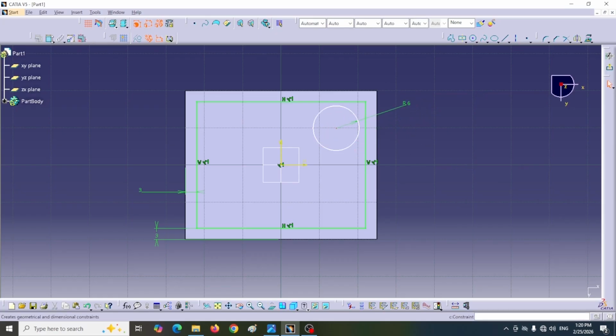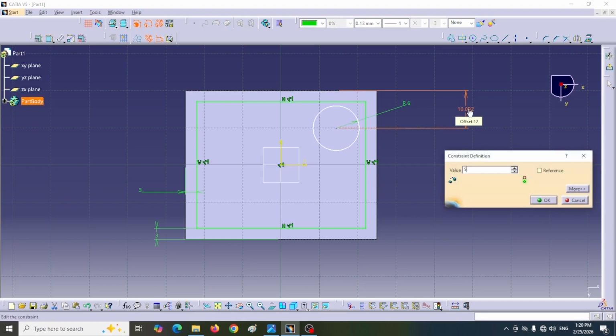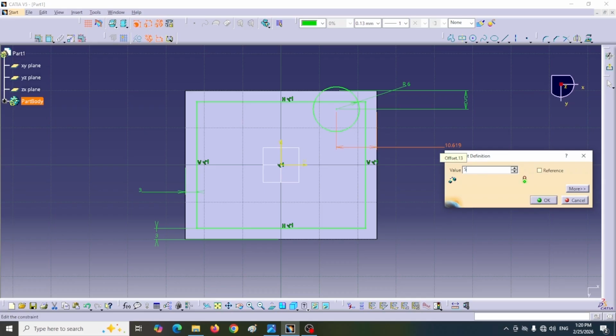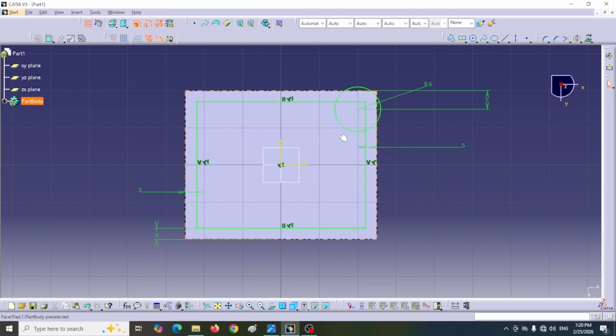Note that if we had applied fillets to the cube corners before, drawing the circles would be easier. In that case, I would use the hole tool and make it concentric to the fillets. But in the drawing, the distance from the circle centers to the cube edges is given, so I draw the circle without fillets.